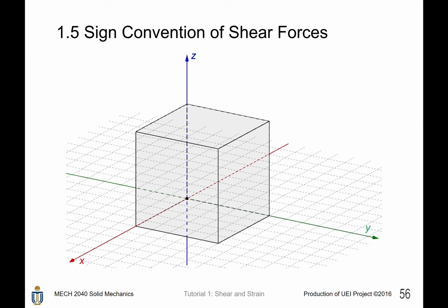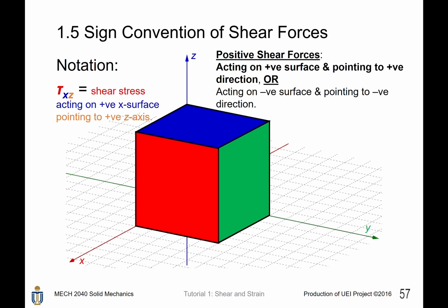After talking about the positivity or negativity of the surface, let's talk about the shear force. For the shear force, we still have to talk about its direction. One important thing I have to mention is that even if you apply a force here that is upward, it is not enough to say it is a positive force. Or if you draw a downward arrow and say it is a negative force, that is still not enough. How can we name those shear forces or shear stresses? What is a positive shear force? A positive shear force acts on a positive surface and points in the positive direction of the axis.